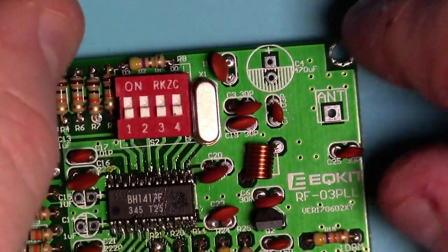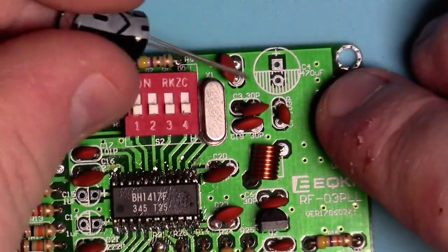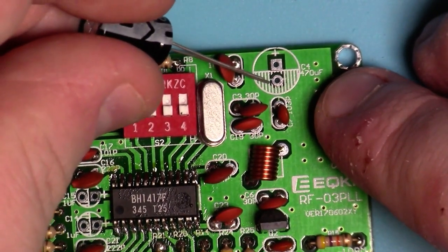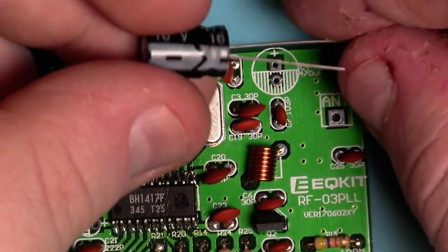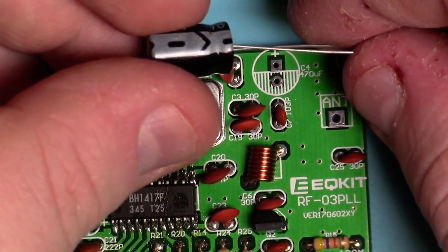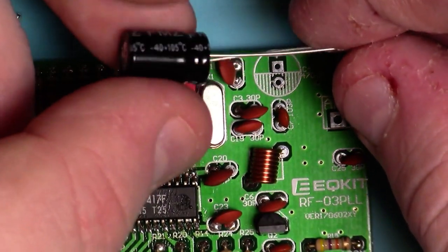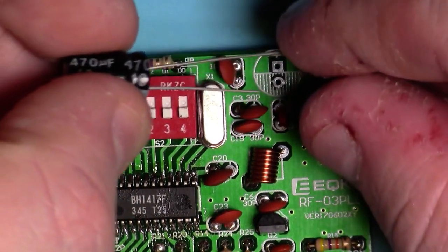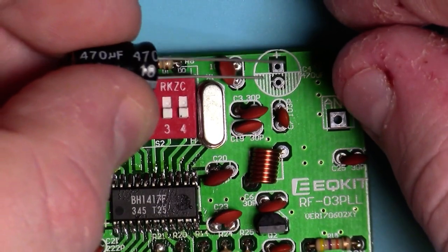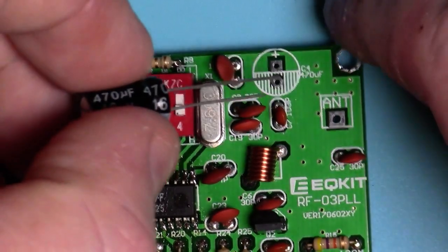You'll see on the PCB we have a marking here. We have a shaded side, and we have a side with a positive. And on the capacitor we have a negative marking, no positive marking, but we have two different sizes of legs, and we want to put these in like that.